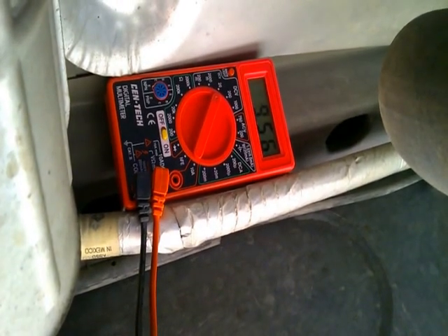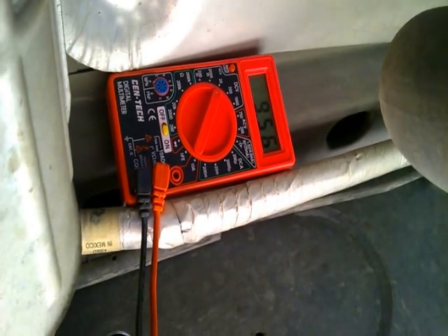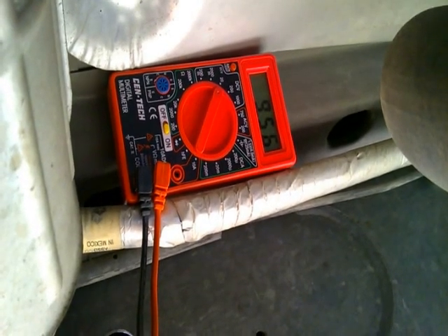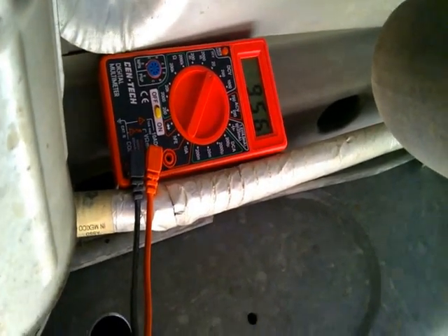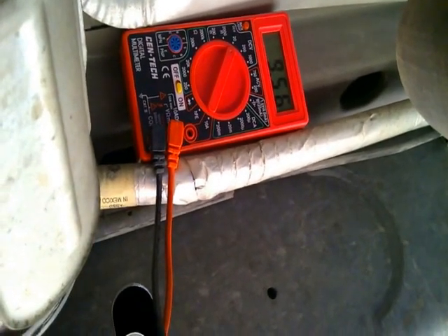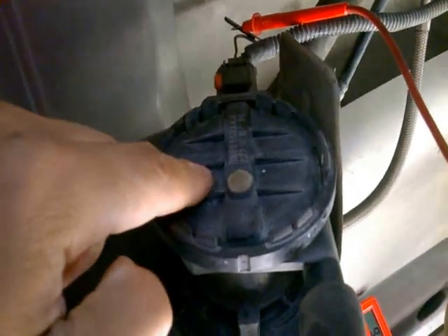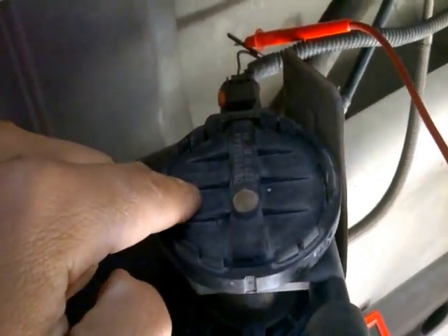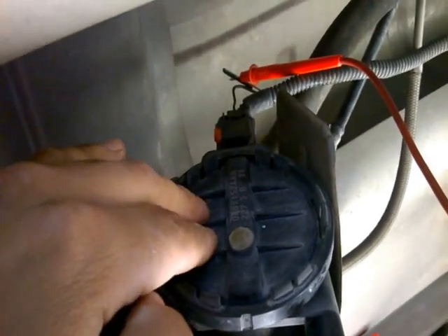Now the next step is to go back to the vacuum pump and apply, like I said, that 1 inch of H2O. With the key off, engine off, the 5-volt reference should drop to 0 volts. That basically confirms that the switch on the natural vacuum leak detector has closed. It has gone from open to closed, which has basically sealed the whole system.